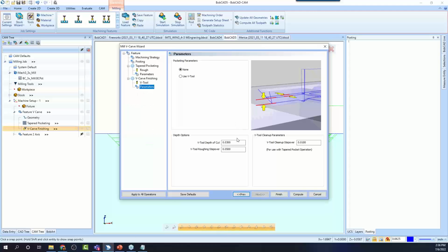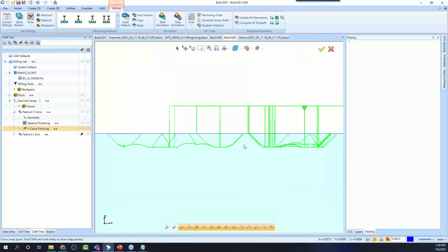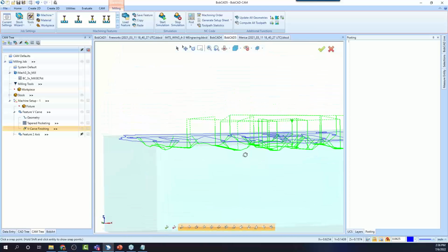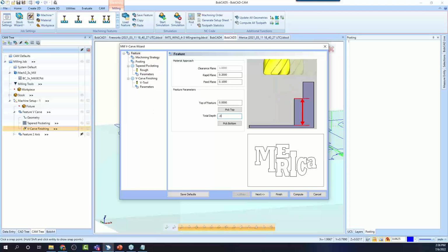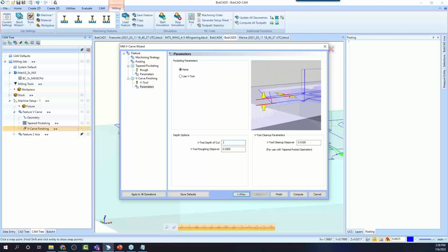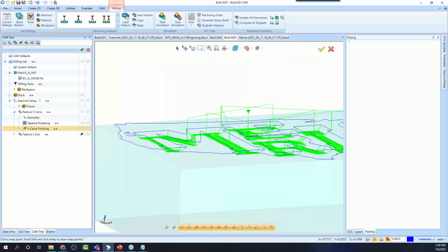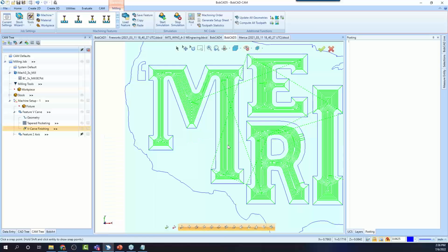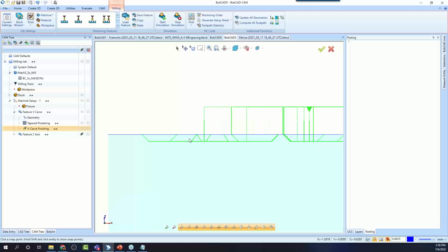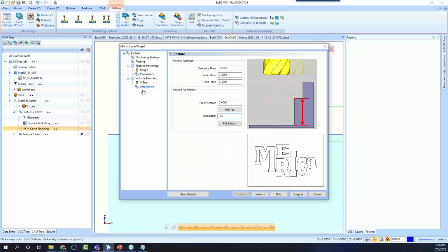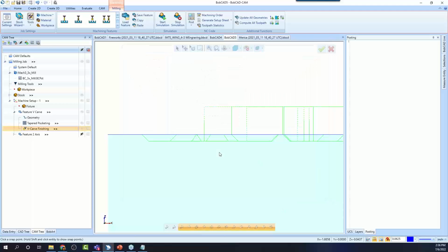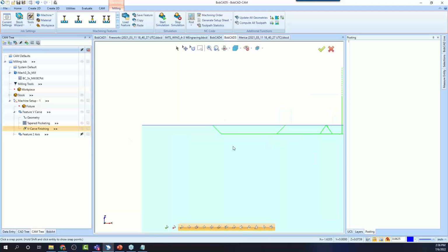At this point, it's going deeper than I want. Let's make this 0.1. And I'm flattening it off. And it's not really clear to me. I think I need to be in a different range, but yes, 0.05. Let's match these two, 0.05. We should see how it's changing the floor, where the floor of the pocket is, right? So let's make this one 0.03, and we'll leave the other one the same. You can see how it's moving this up or down. So you can control the depth of that pocket.